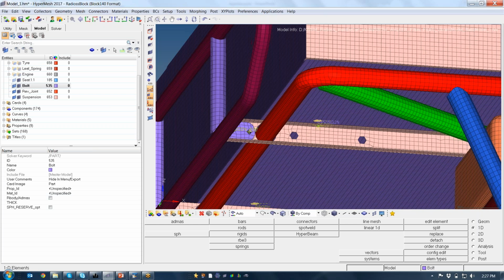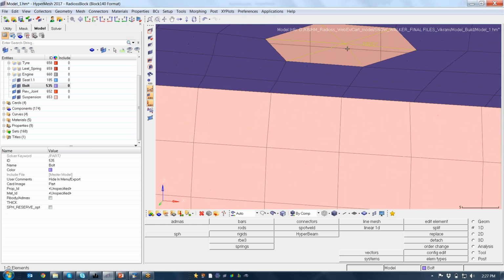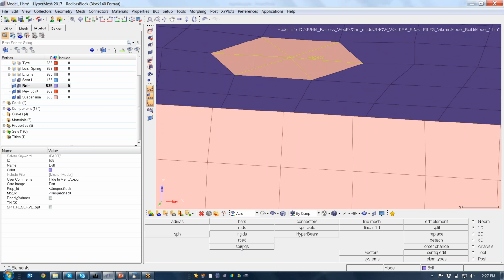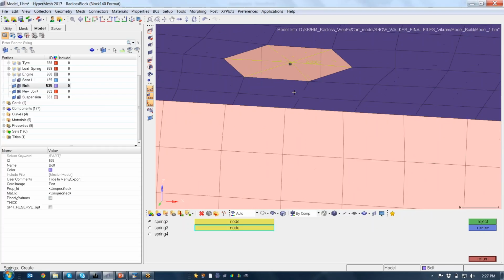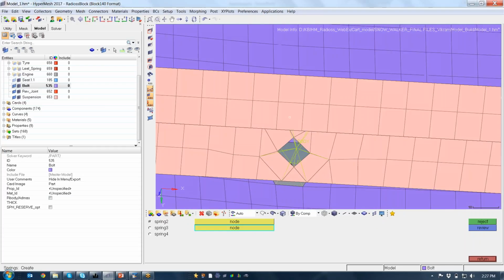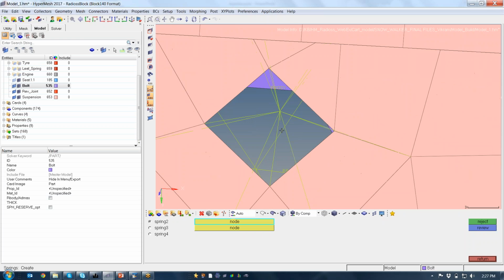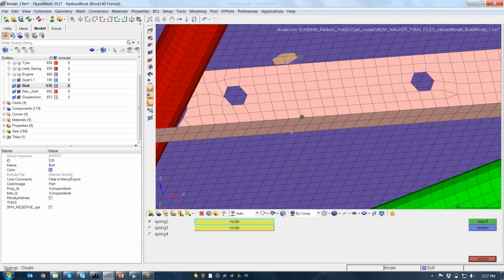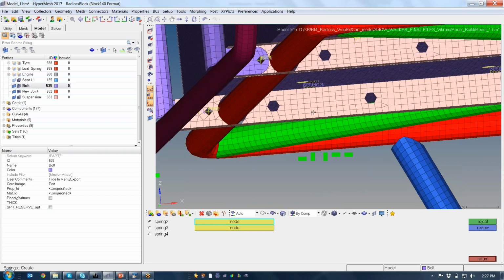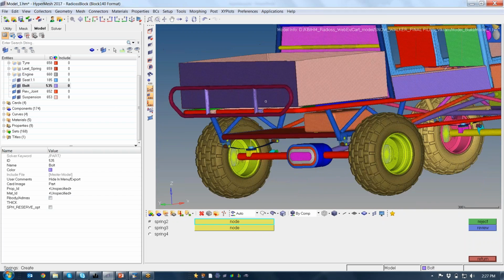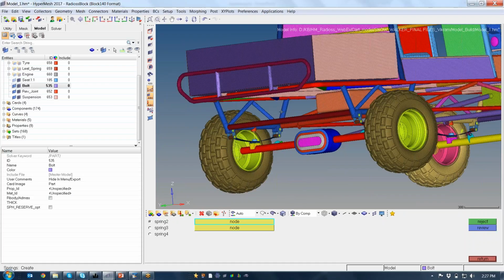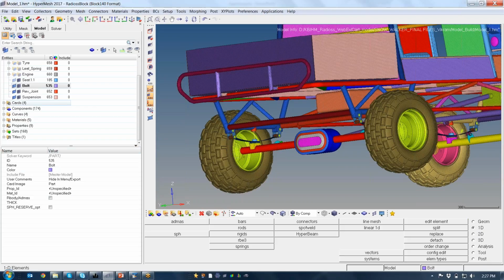Now in that location I already have a bolt, so here I have to create a bolt. So again the procedure is the same. I will select 2 nodes, and I'll create a bolt. Okay. So just now we created one suspension element, one revolute joint, and a bolt, and all are having different properties as you have seen. Okay, now the element creation is over, but I have just created the property and have not updated it. Okay, so let me update them.